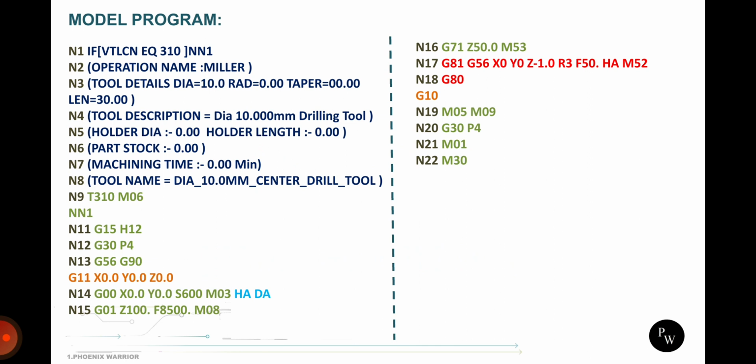So if we want to move the entire program for the current work offset, say we want to move in the positive direction in the X axis by 100 mm, we can directly give X100. If we want to move in Y minus 100, we can give that directly. So we don't need to disturb the work offset, we can alter the single program. So the remaining programs run as per the work coordinate system. So we can adjust in each and every individual program.